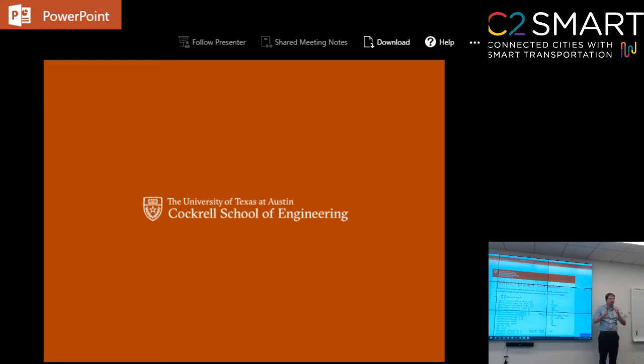So it's true that in reality, the OD coefficients, I mean the junction coefficients, will be affected by the state of the traffic. Here we don't take that into account. There is no interaction between the state and the model parameters. Model parameters are set once and for all, but because of that robust formulation, you can still take that into account somehow. Even though people will change their route choice, and that's not part of the model, because of that uncertainty in the ratio, you still somehow take that into account.